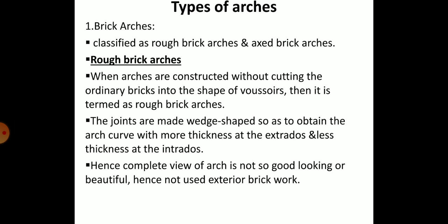So we will start with the brick arches. The classification of the brick arch is rough brick arch and axed brick arch. So we will go with the rough brick arch. First of all, what are brick arches? These are mainly classified as rough brick arches and axed brick arches, or rough cut brick arches. So what are rough brick arches? When arches are constructed without cutting the ordinary bricks into the shape of voussoirs, they are termed rough brick arches.